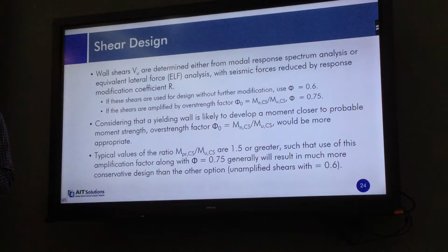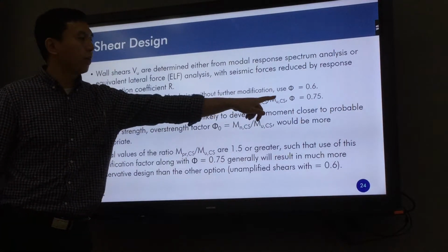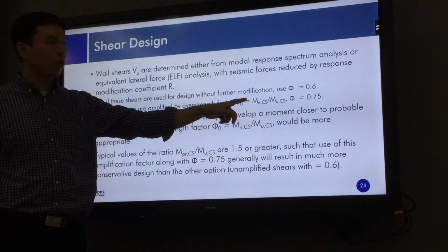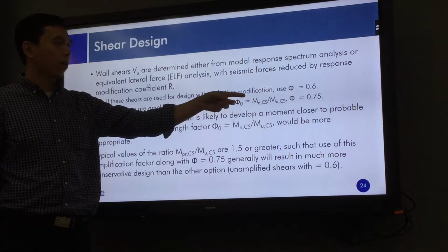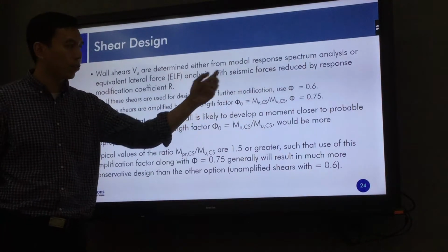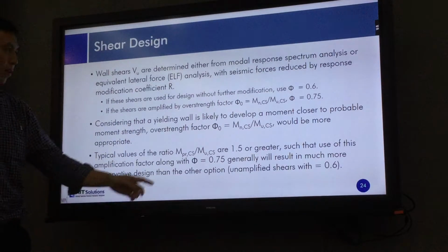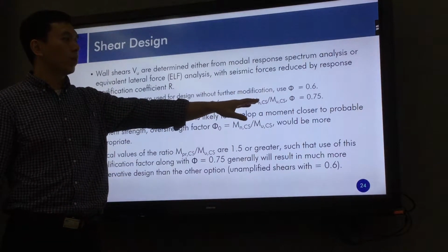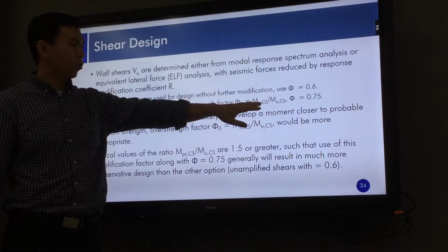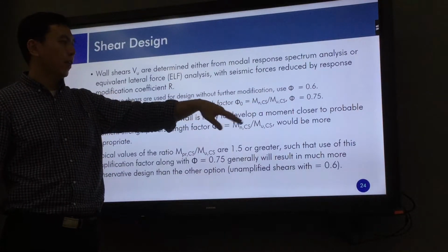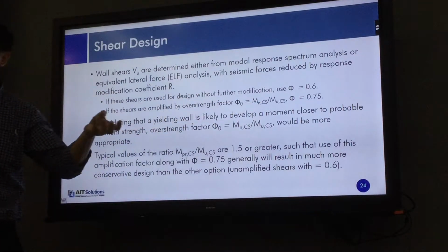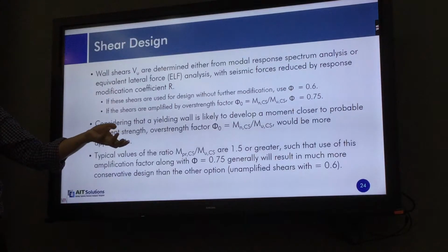So for example, if your shear demand from the load combination is 10,000 kilonewton, and this is like a moment DC ratio, you design the shear wall for a demand to capacity ratio of 0.8. So it will be 1 over 0.8, and you will get the factor and multiply that factor with the shear demand.